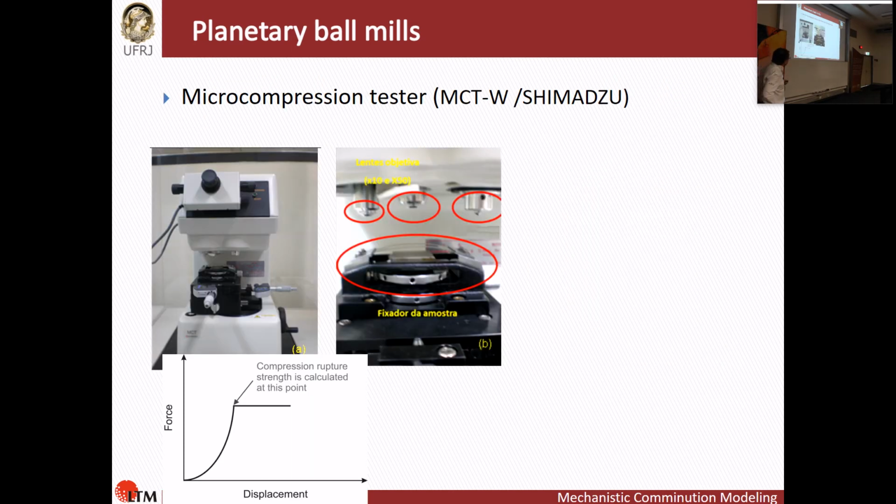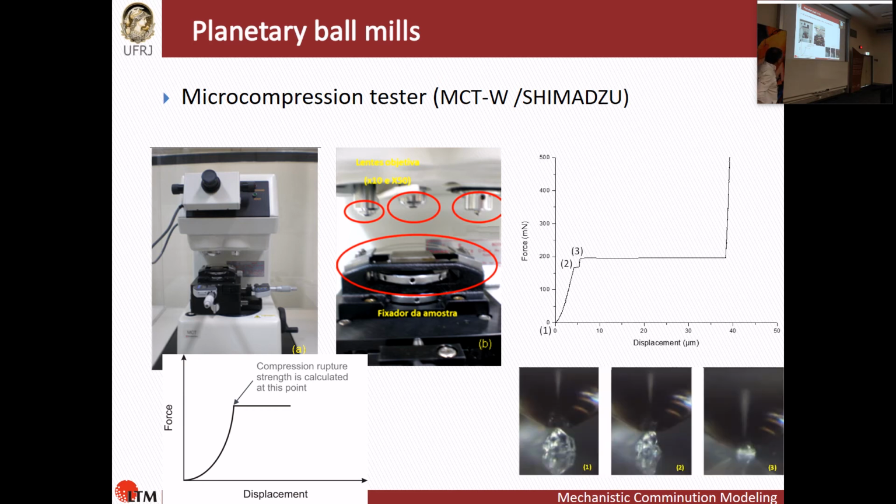And so, now the major question arises: how can you measure strengths of particles which are that fine? You cannot really even grab individual particles. Now, these days there are machines like this, which are basically indenters with a blunt indenter to crush, like a small compression test. And so you can actually test particles one by one. For instance, for a small 40 micron quartz particle, you can get exactly the force-deformation profile and determine the amount of energy.